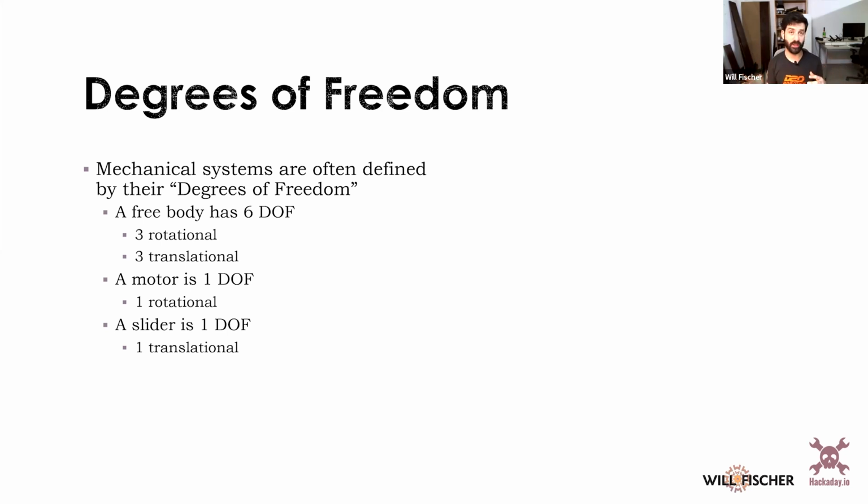If they don't operate independently, maybe you've synced them together with gears, then it's only a 1 degree of freedom system. And that's actually really convenient. That can be a really nice way to do it. And you see this sometimes out in the field where gearing or linkages create a single degree of freedom system. I'll show you a really cool single degree of freedom system when we get to the linkages stuff later on.